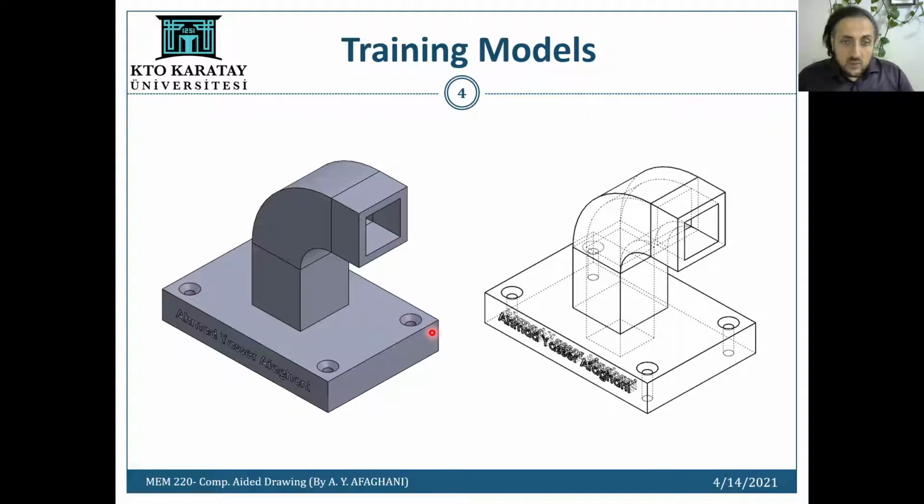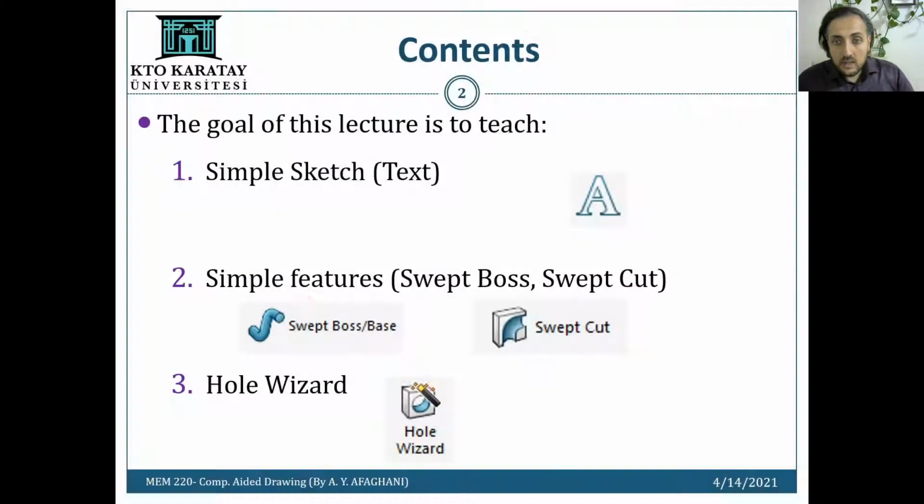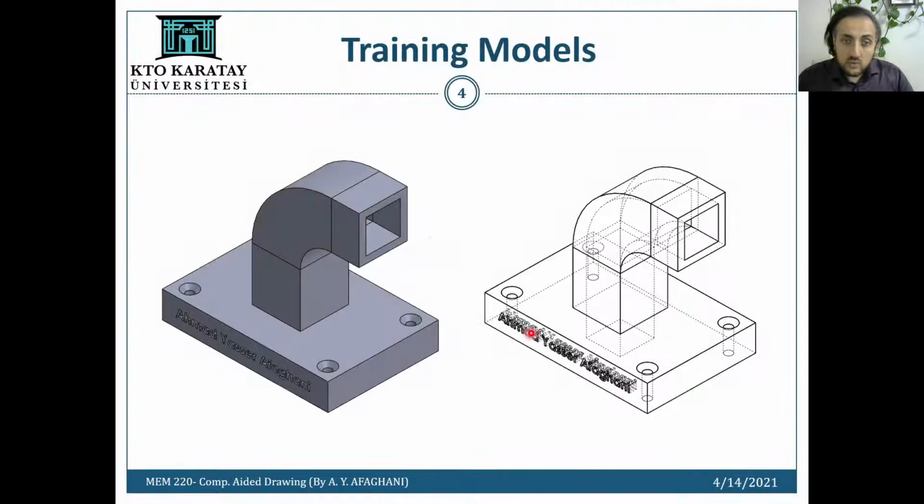You will feel it's actually very easy. It's only a rectangle with some extruded boss. Then I have here a canal, but it's a curved canal. So actually, how can we design this type of canal? There are many techniques, but today I will teach you how to use the swept boss, in addition to swept cut, in order to cut inside this canal, plus the hole wizard.